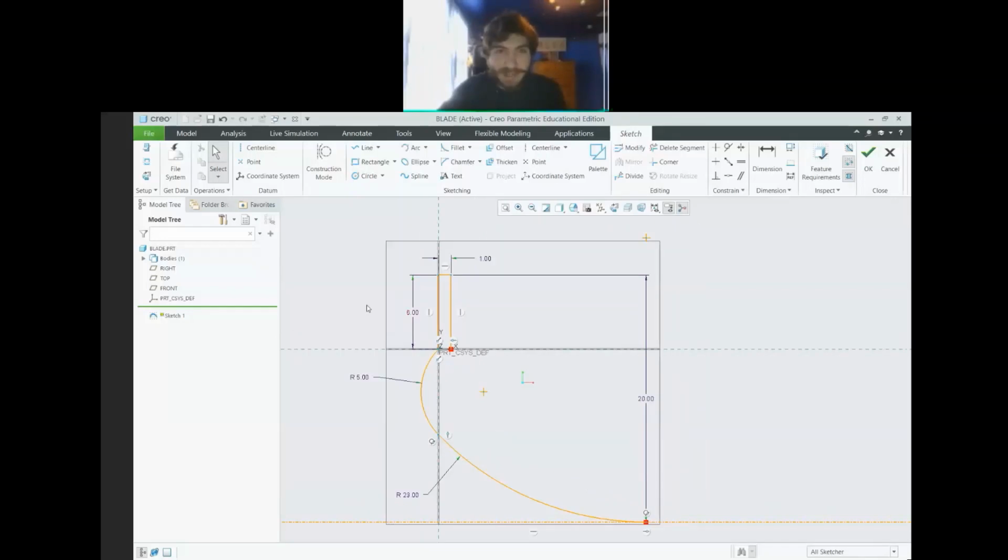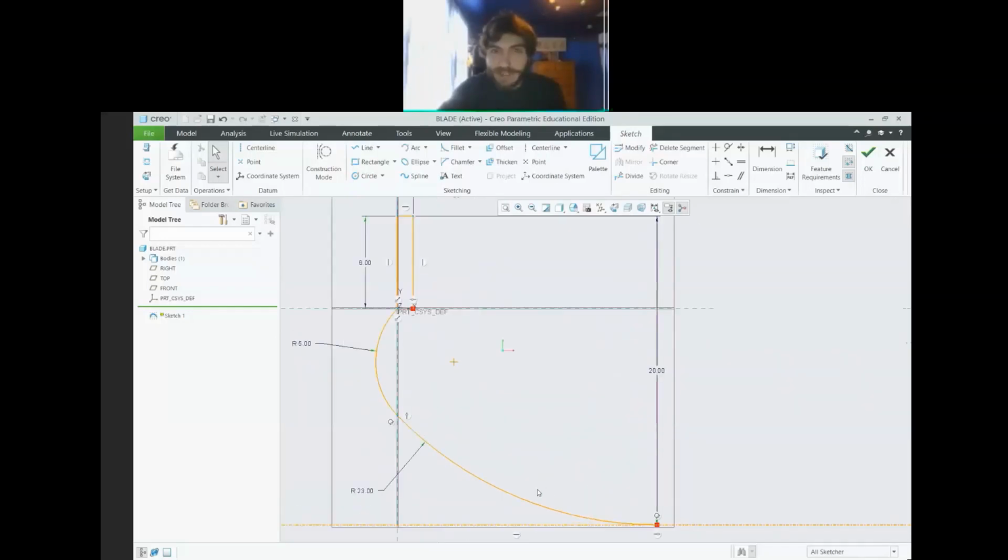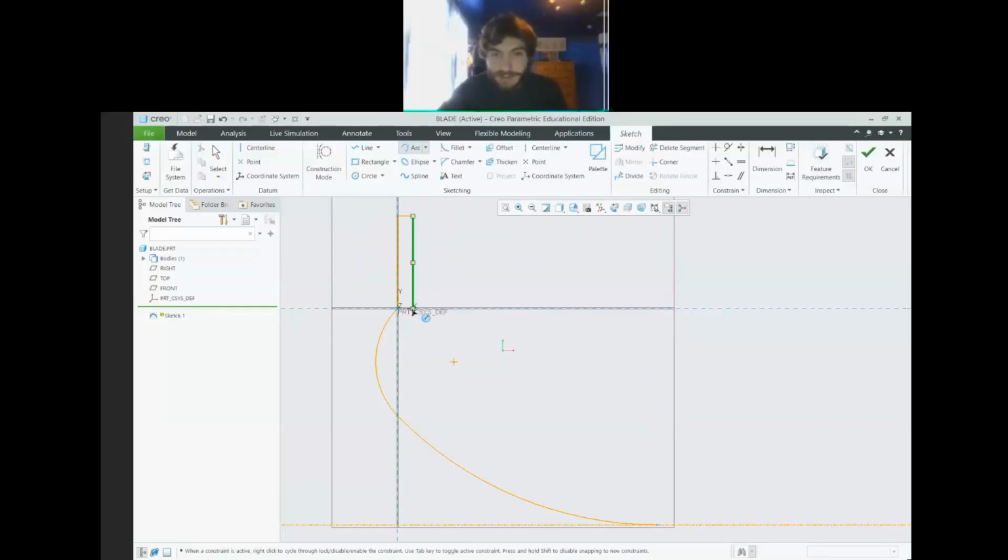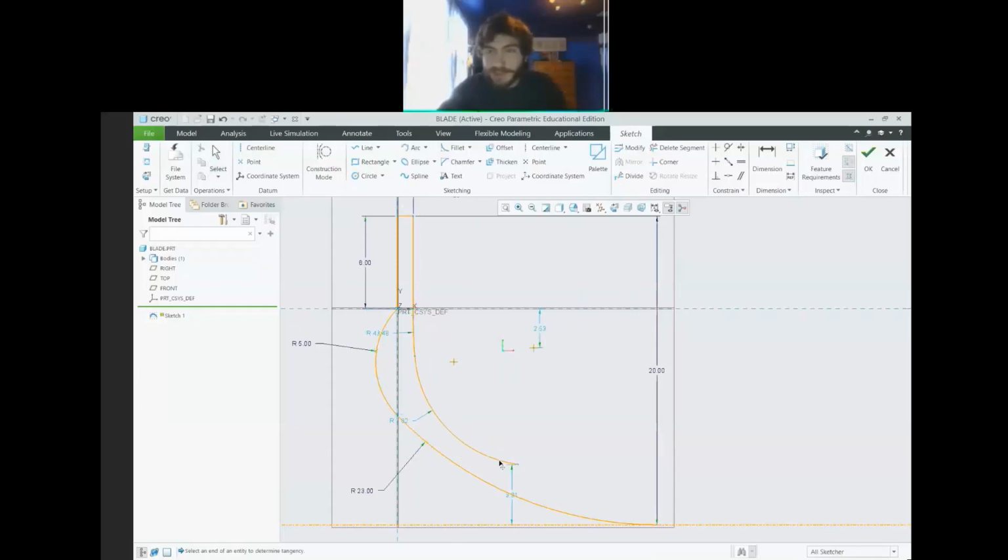All right, so there are a couple ways to do the next part. We'll do maybe what's the easiest. We'll go back to this arc tool, the three points, and create another arc, and then we just create our two arcs. That's fine. And so we're going to come up to our constraints here again, and these two horizontal lines is our equal constraint. We'll click our first arc and our second, and now they become the same arc.